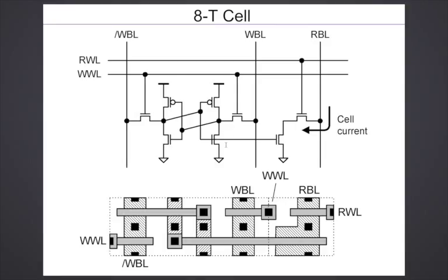So anytime you make a change to the cell, you also have to pay attention to the layout. So this is the layout of the cell. Nowadays all memory cells are done in this kind of flat architecture for the layout. You see, this is one of the inverters, where you have an NMOS, then the PMOS of the inverter, and this is the gate of the inverter.